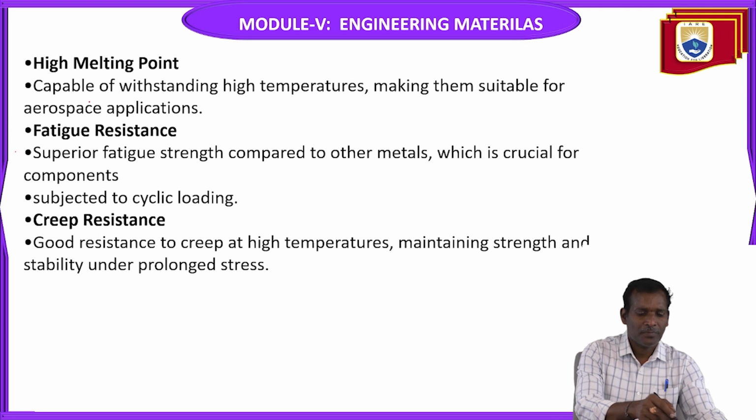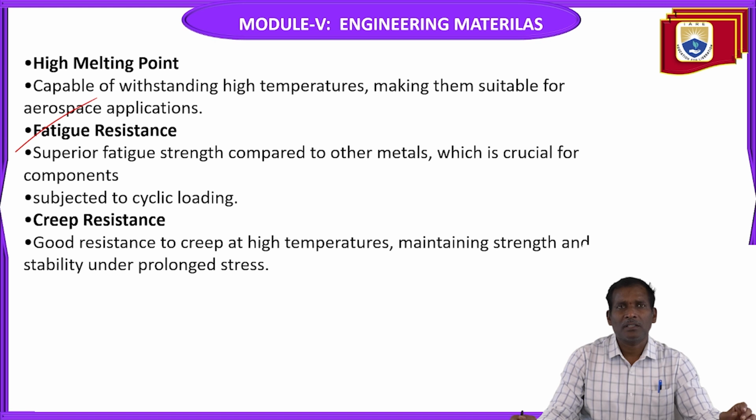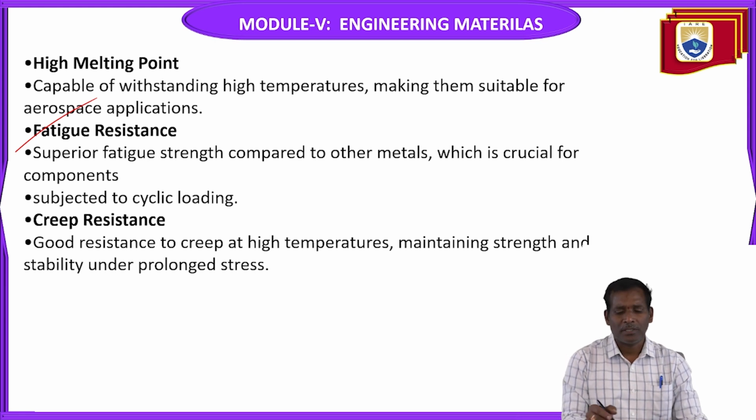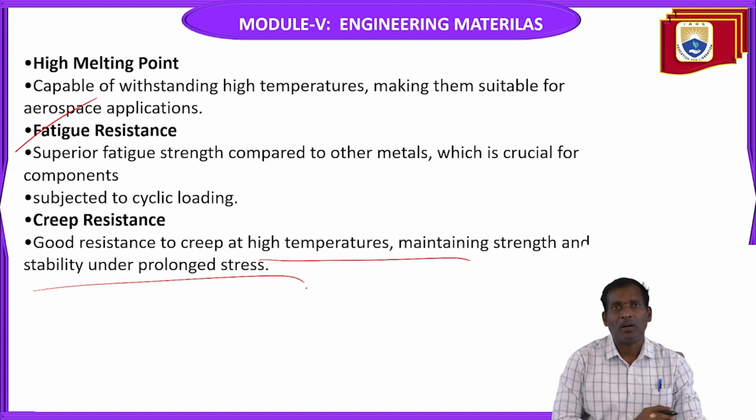The fatigue resistance: superior fatigue strength compared to other metals, which is crucial for components subjected to cyclic loading. Fatigue is a mechanical property. Whenever a component is subjected to cyclic loading, it will fail after a certain number of cycles. The creep resistance: good resistance to creep at high temperatures, maintaining strength and stability under prolonged stress.